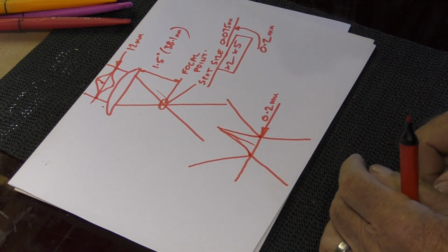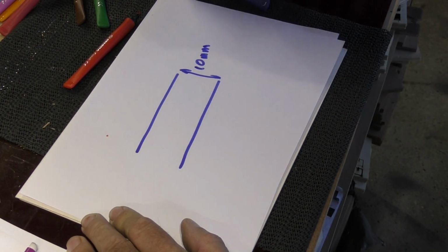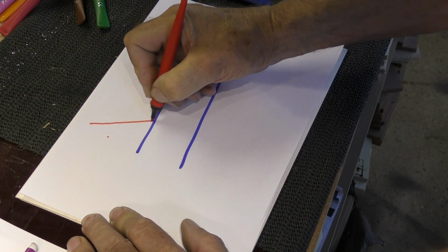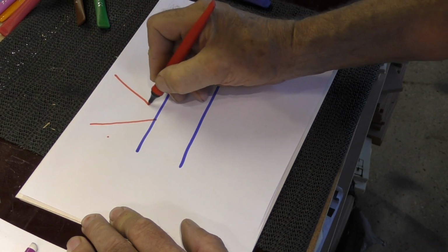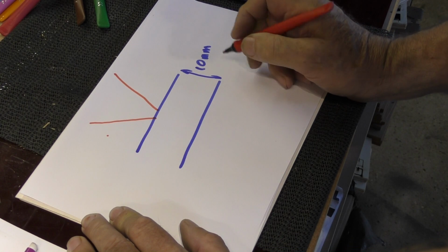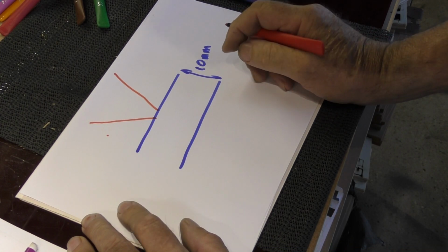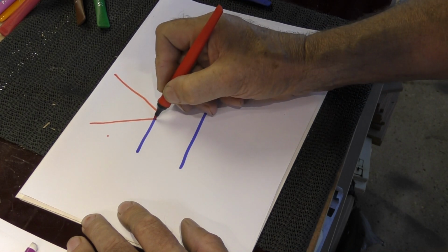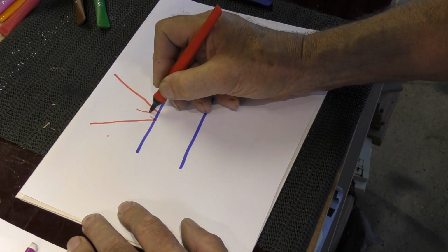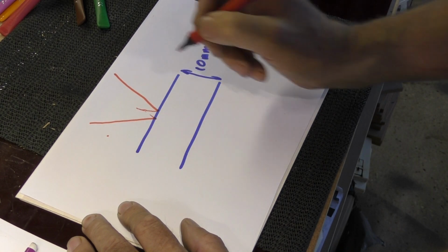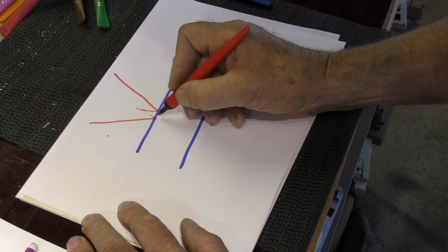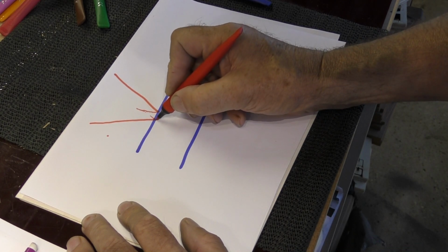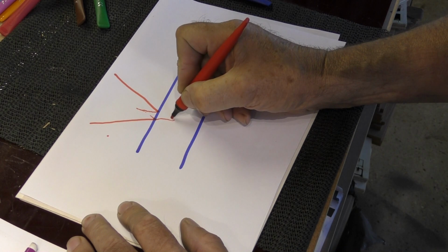Let's move on to another piece of paper. I've got some 10mm material, and I am going to be firing the laser beam at a spot on the surface, the focal point. My theory is this. At that point there, we've seen that we've got this incredibly high energy distribution at the centre. We're going to see a mode burn which effectively looks like this.